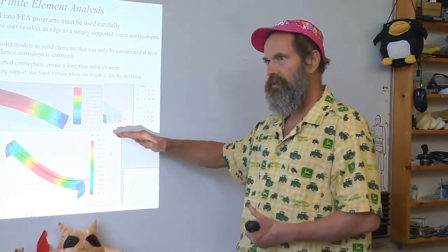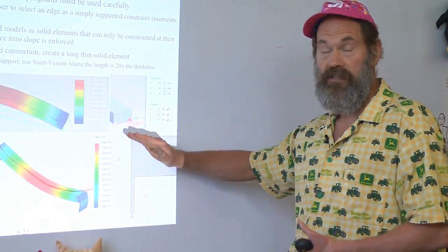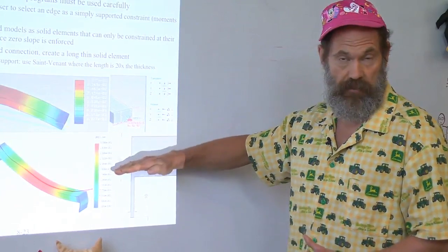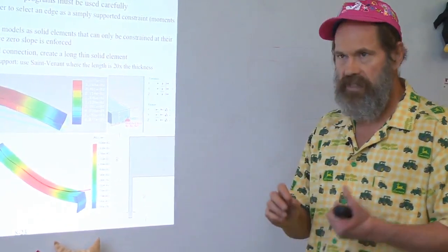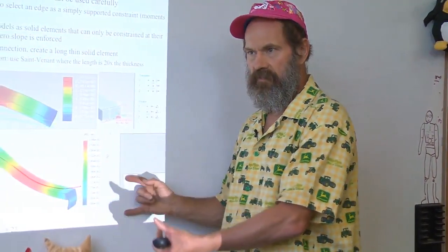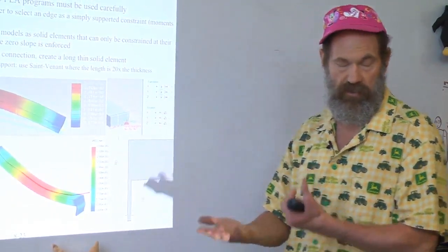to free up the anchoring stiffness so it behaves the way it's actually going to behave in the machine, while maintaining, for example, the linear stiffness in the directions where you know it's going to be stiff. Similar modes of thinking apply for torsion. So do not be afraid in your solid model layout of your structure to add in compliance cuts or compliance structures to enable the finite element results to be accurate.